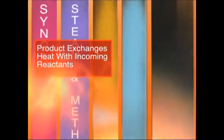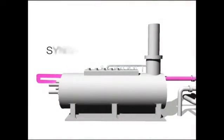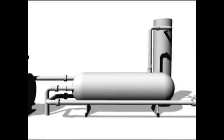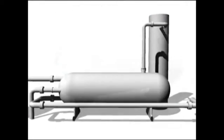While exiting the reactor block, the product gas exchanges heat with the incoming methane and steam. Combustion exhaust leaves through the stack on the top of the assembly. Synthesis gas exits the assembly through a manifold similar to the inlet headers. The next major unit in the gas-to-liquids process is Fischer-Tropsch or FT synthesis. Microchannel technology also improves this step.